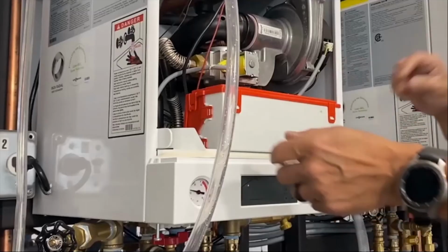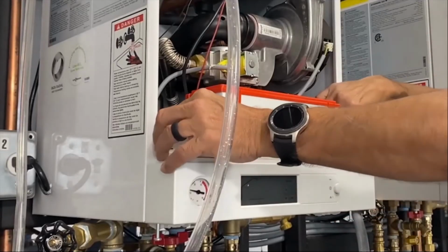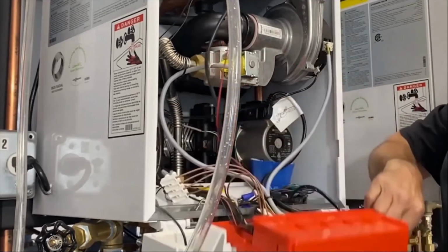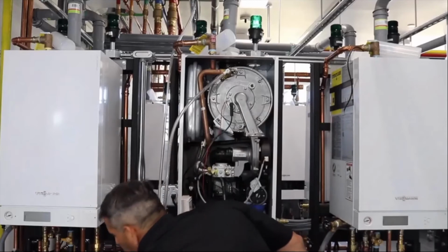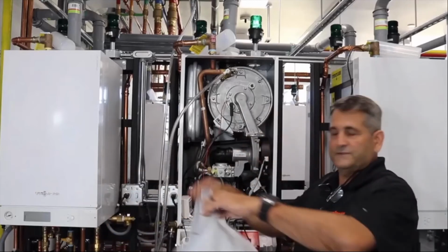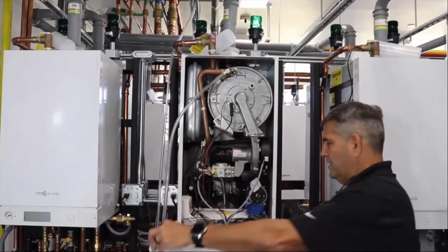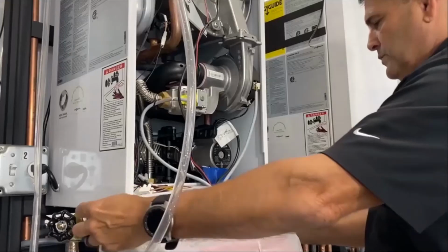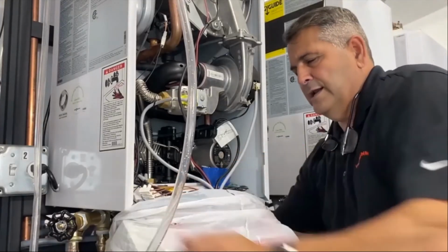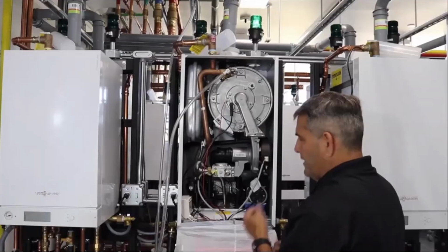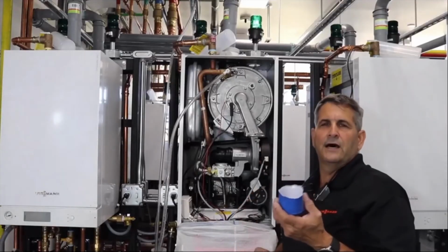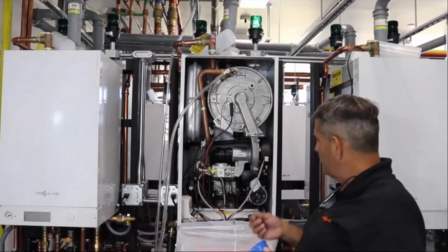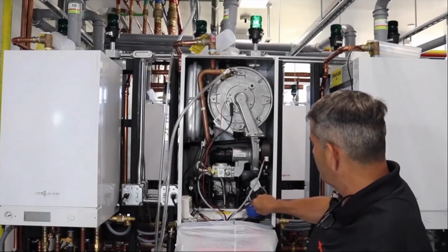To do that, we're going to take the 2 tabs, squeeze them, and then pull down the control. If you don't feel comfortable with the water situation, get yourself just a cheap plastic bag and cover your control. That way we're not going to get any water on the control itself. I did take the liberty and cut a little cup in half. You're not going to get a lot of water out of the pump, but we want to check the pump because the shaft could be frozen